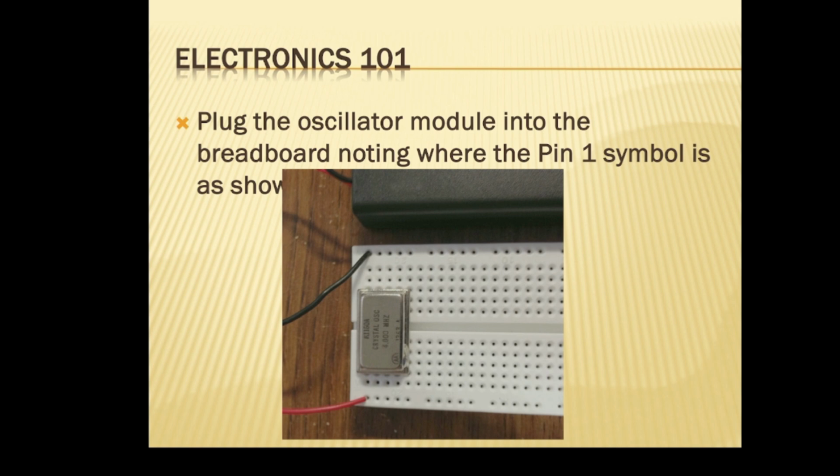So everybody says you should turn off the power while working on circuitry. Yeah, you really should. Every electrician says so, and no one ever does. That particular capacitor is taking all the signal out. We need a smaller value capacitor there. It's basically sucking all the signal. That's okay. We get the idea. You see it's starting to round, and we get down to here on the end when it should be even rounder still.